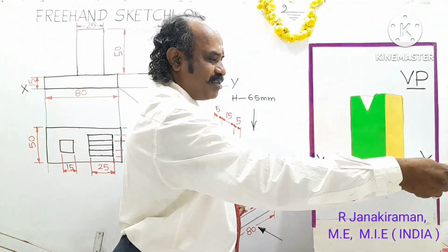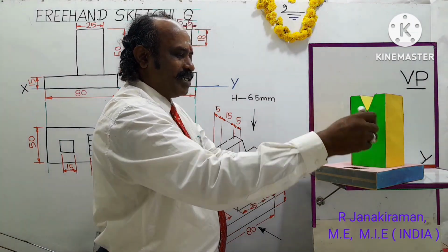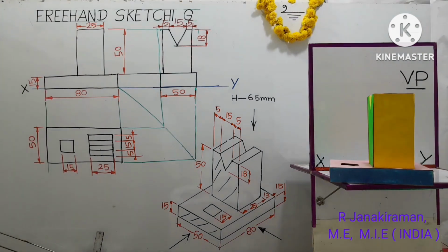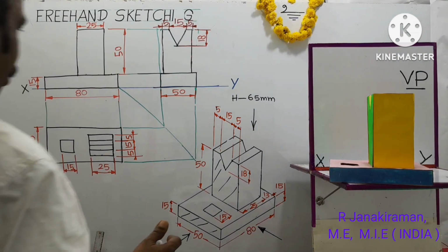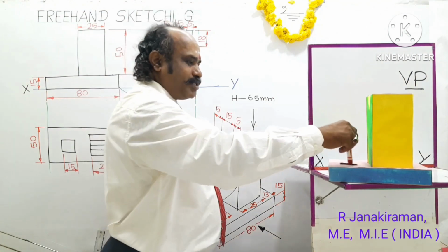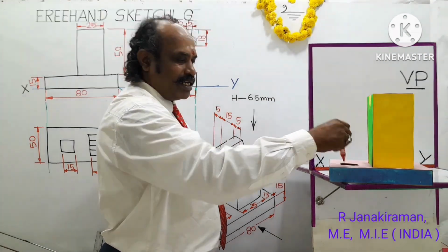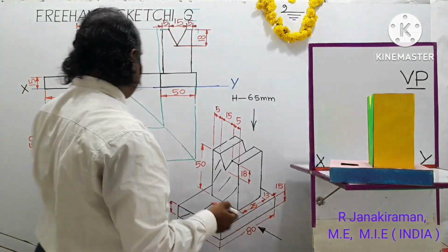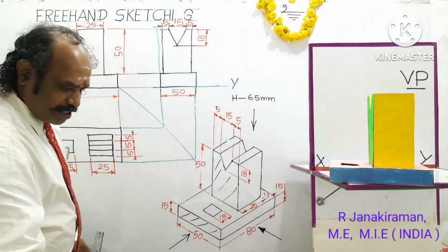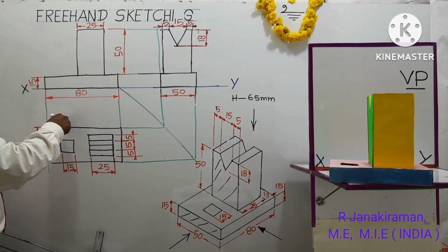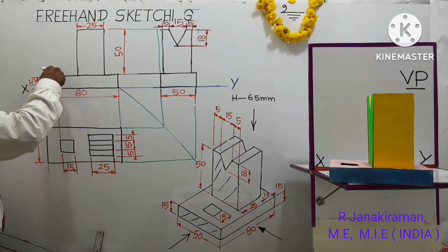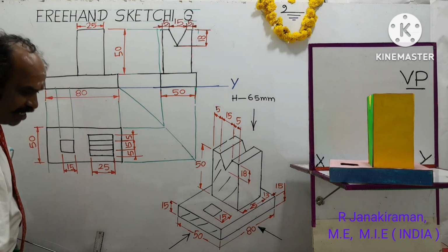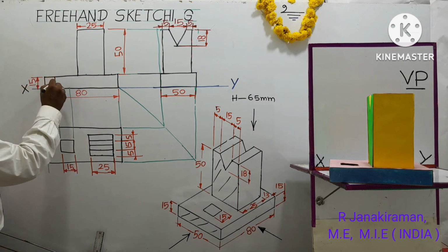Okay. The observer cannot see the square hole available at the inside. So I turn the object so that you can see it in the camera. The square hole is a hollow passage along the base of this object. Something is passing inside. That is not seen in this front view direction. That has to be indicated in the diagram by means of a dashed line. So trace out this square hole of size about 15 mm by 2H pencil. Where it intersects with the base, there you draw a dashed line to show the hidden part.